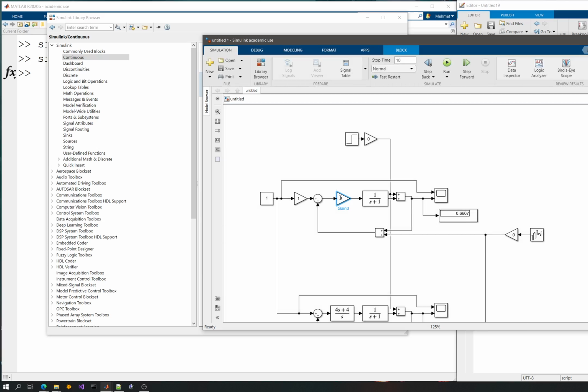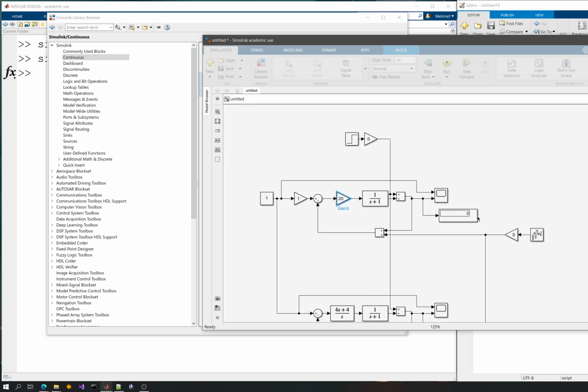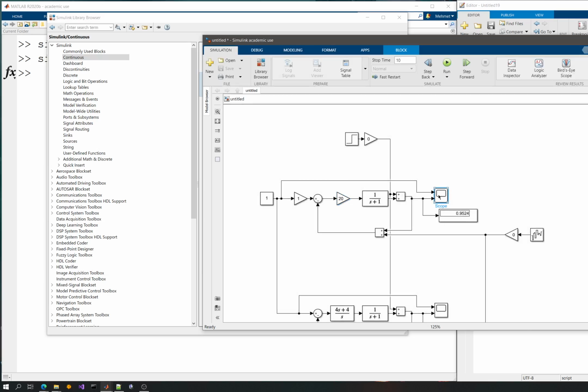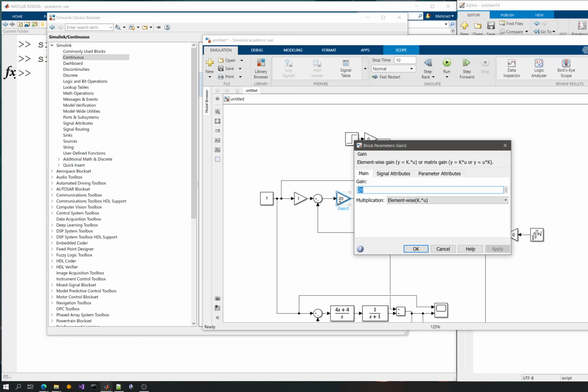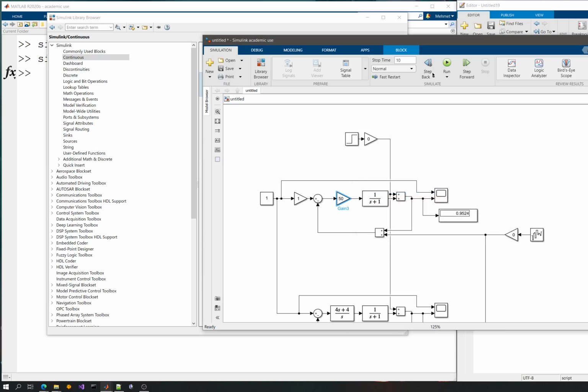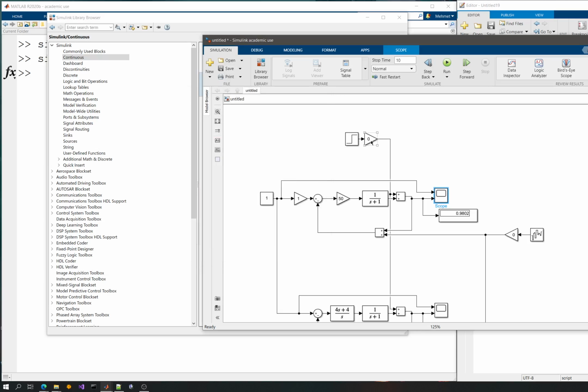So having a high gain is most of the time a good idea for the P-type controller to have less steady state error. And if you have 100 basically, or let's say 50, it should basically almost vanish. It means 2%, which is basically the definition of settling time. So if it's like this, we can assume this as settling time, but you will see that having an effect with the disturbance will be a problem on its own.